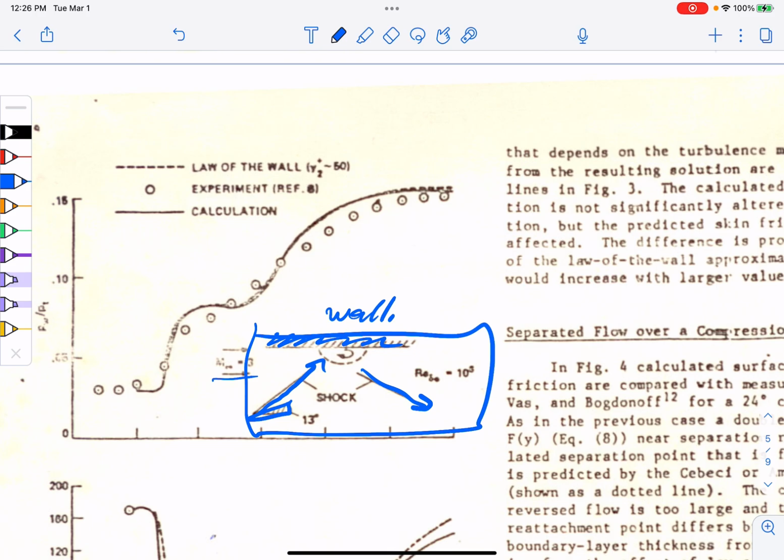So this is a turbulent flow. It's unsteady. And there's a little issue with this now. Because you remember in compressible flow class, when we said, oh, we have a 2D flow, maybe we have the Euler equations, and we just have a nice perfect reflection. But there's a turbulent boundary layer, and when a shock wave, often oblique, hits a supersonic turbulent boundary layer, it's going to reflect off, just like in the inviscid case, but sometimes a recirculation bubble will form at the wall.